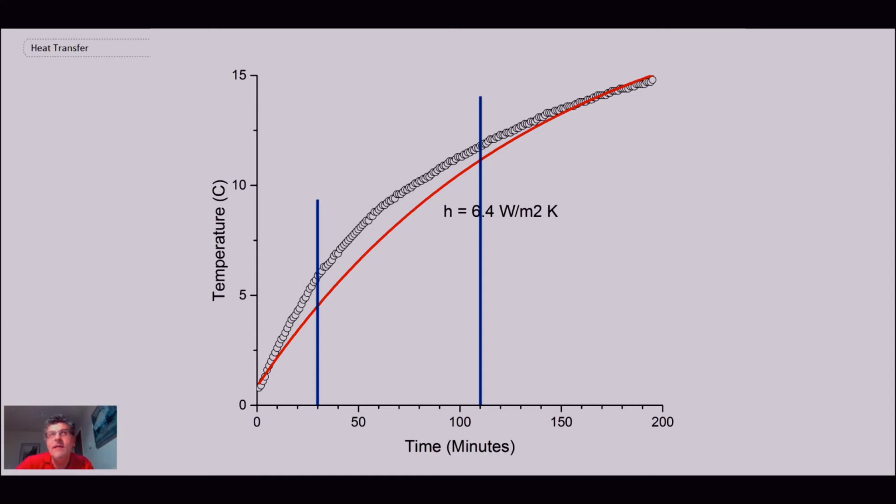And in there, that is a strong indication that the lumped capacitance technique does not apply in that region. Consequently, that's probably also why it's kind of hard to fit the curve, as shown by the difference between the raw data and the red curve, which shows the results of the lumped capacitance assuming that the convective heat transfer coefficient was 6.4 watts per square meter Kelvin. What is the cause of that? It's difficult to speculate. I think we need further experiments.